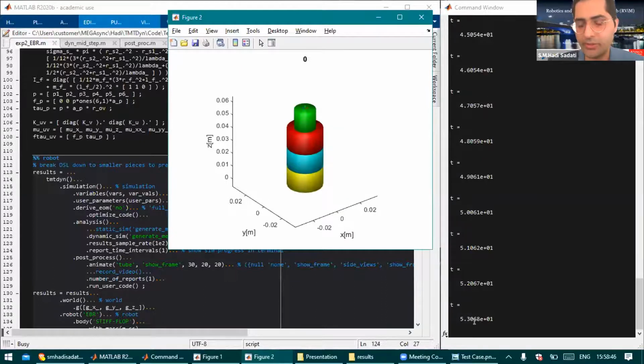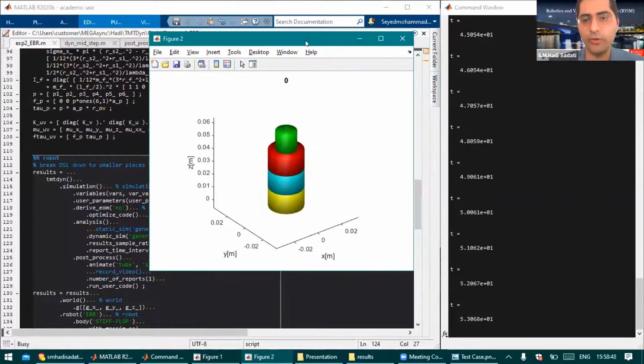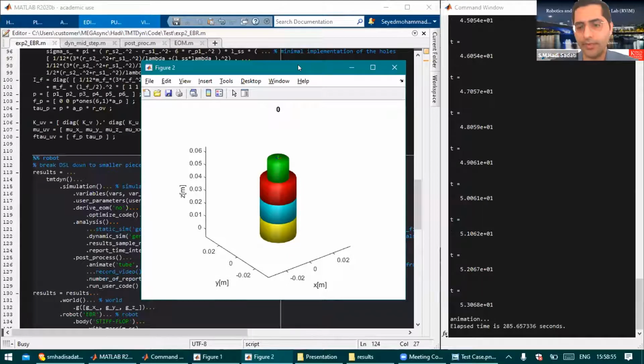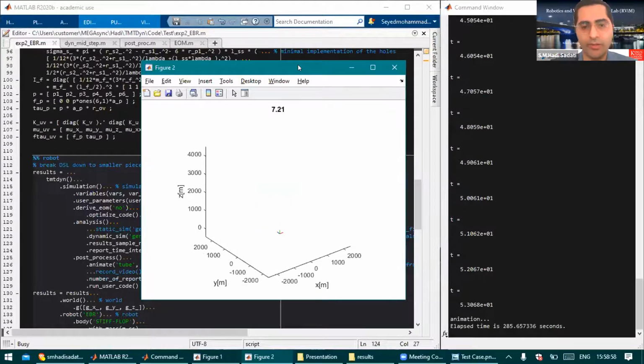Okay, the simulation is almost over. Yep, done. Now it calculates the animation for you. Oh, and it's going to elongate a lot. So yeah, it diverged. Sorry for that. It obviously diverged. You see, it elongates 20 times the pressure. It basically elongates the system 4,000 times of initial length. Okay, probably I should have set it to 2, not to any.